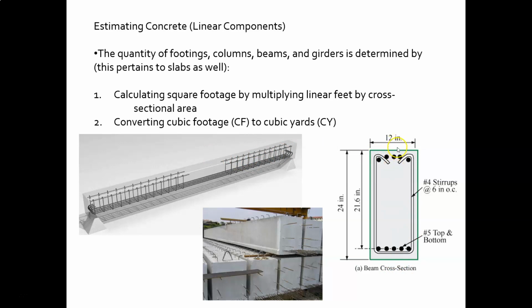And so this is double reinforced, and here we see some precast beams with the same. A lot of steel rebar reinforcement across the bottom because beams are weak in tension, so they need rebar at the bottom, and then we see some other rebar coming from the side. So very similar, and these are possibly the heads of stirrups. Okay, so that's what we're looking at, the cross section.